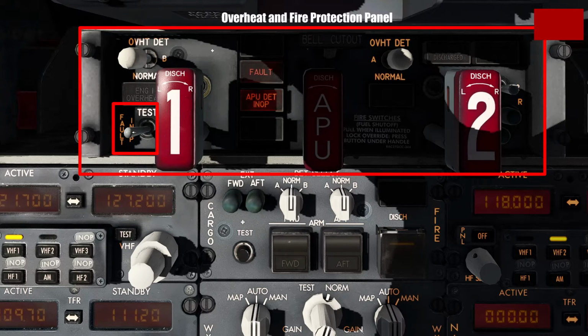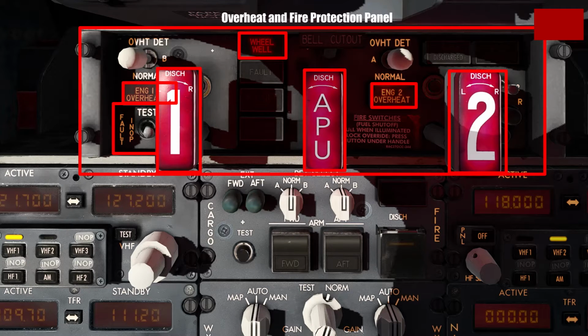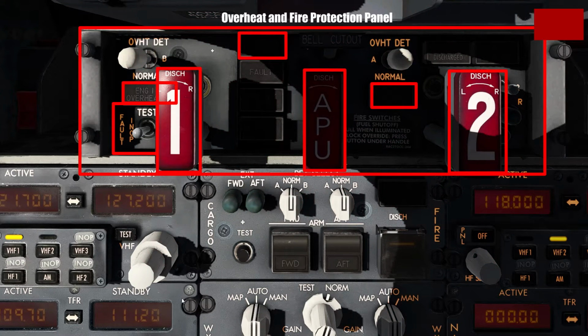Flicking it to the left simply allows pilots to test whether the engine and APU's fire detection units' fault and inoperative lights are working as intended. Flicking the same switch to the right tests these two engine overheat lights, this wheel well overheat light, signifying a possible fire in the main landing gear compartment of the aircraft, as well as lights up these three large red lights in the middle. Additionally, a blaring alarm is also sounded to alert the pilots that there is an imminent danger on board, like so.